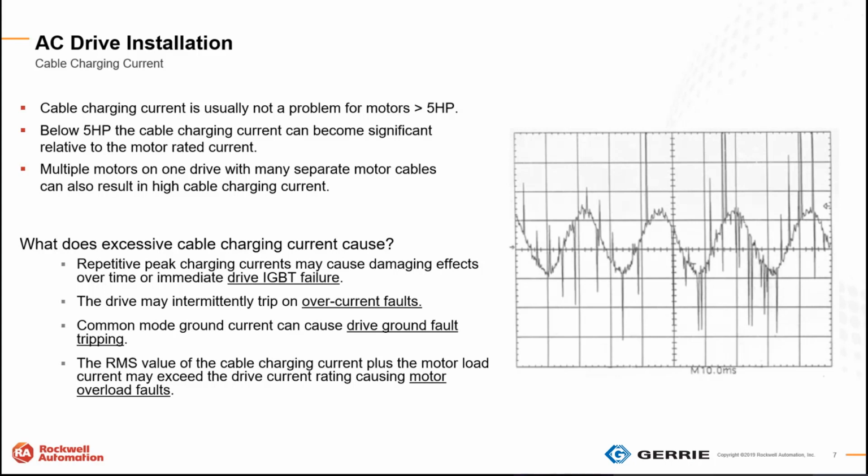That extra current, that high frequency, is induced because our grounding conductor is running in parallel with our 3-phase motor leads. We may get induced charging currents back onto the ground and may have a ground fault issue. But typically it comes back as a motor overload fault. Because we're estimating the overload of the motor, and that extra current going out is being consumed by the capacitance of the cable, the drive tends to think that we're overheating the motor. The motor is drawing a lot of current based upon the FLA of the motor that we put in. So we'll see that as well.